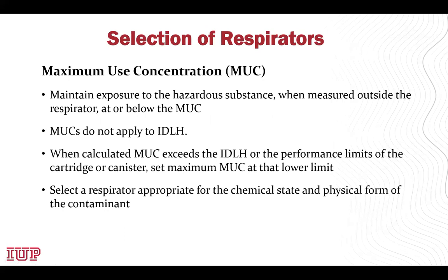Maximum use concentration: you must select a respirator that maintains exposure to the hazardous substance, when measured outside the respirator, at or below the maximum use concentration. The MUCs do not apply to IDLH atmospheres. When the calculated MUC exceeds the IDLH atmosphere or the performance limits of the cartridge or canister, set the maximum use concentration at the lower limit. Select a respirator appropriate for the chemical state and physical form of the contaminant.